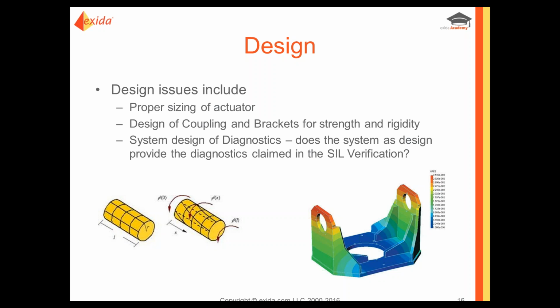Now, back to design. We need to size the actuator to the valve correctly. Then things like mounting brackets and couplings have to be designed to have the strength, not just strength, but rigidity, so we don't get misalignment over time, to do the job.